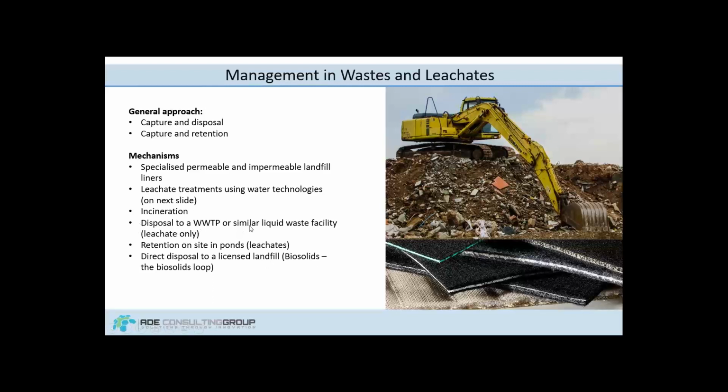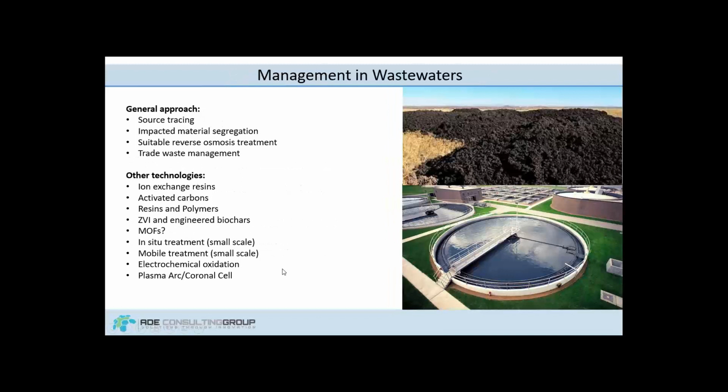So looking at the points on wastewater treatment plants and disposal of biosolids, there's kind of a loop there because you have PFAS leaving landfill and leachate going to the wastewater treatment plant. PFAS at the wastewater treatment plant binding to solids, and then in some cases, biosolids are applied to land, as I mentioned earlier. However, in other cases, it's disposed to landfill, where it again enters the leachate, and we have to continue managing it in that cycle. So that's an important and interesting point. So management in wastewaters. I'm just quickly running through these, and we'll get on to some other items after this.